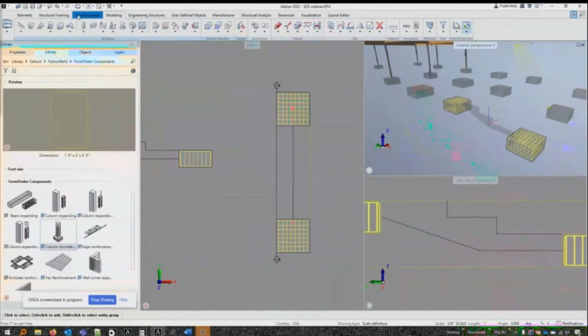And I want to look at some of our modeling tools that we have here. This is actually based on Siemens Parasolid modeling technology. We bought it from them. It's super high powered, does all the stuff you need for constructive solid geometry. We have all of our primitives, our box, our spheres, our cylinders, what have you. From that, we can do the old push-pull. We can loft, we can sweep, we can do revolutions. With these 3D things, we can get center of gravity, do chamfers, fillets, what have you.